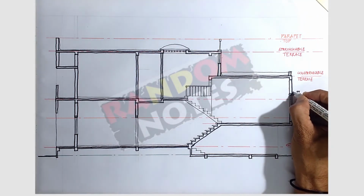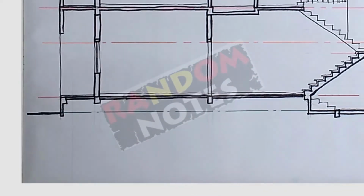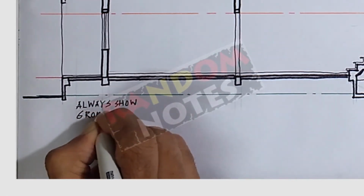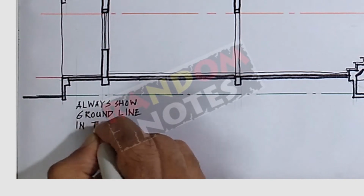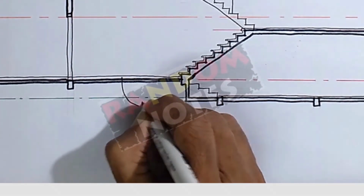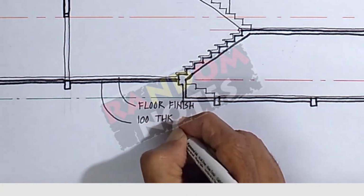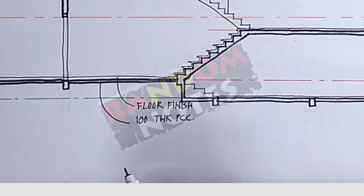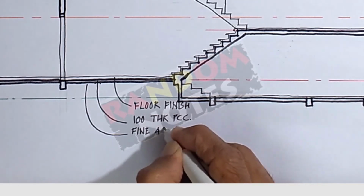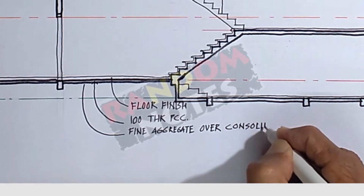Now let us revise some of the important things to be kept in mind. Always show the ground in thick line. The floor resting on ground has to be filled and treated in a manner that it does not sink or settle down. It has layers of materials put in a sequence so that all spaces are filled conveniently and properly to ensure compacted space between the ground and the floor.